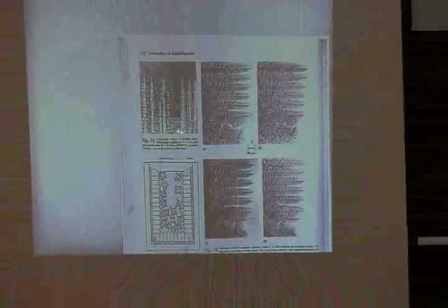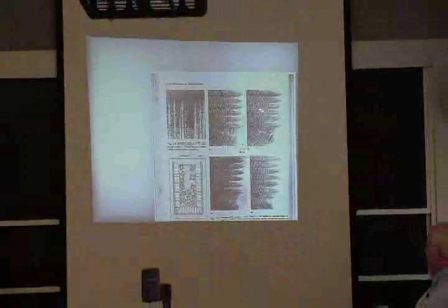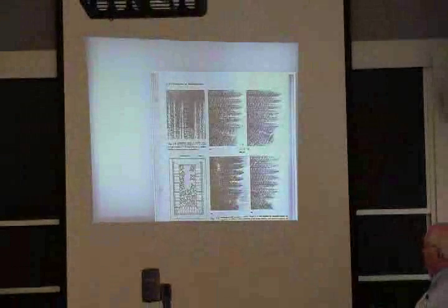But these are 10-20% directionally solidified. These are probably tin dendrites growing into a lead matrix, or vice versa, I guess. It's got to be one or the other. But you can see the dendrites melting at a higher temperature. You've got liquid, the darker liquid here, and this is all solidified stuff. And you get these dendrites form in different ways.